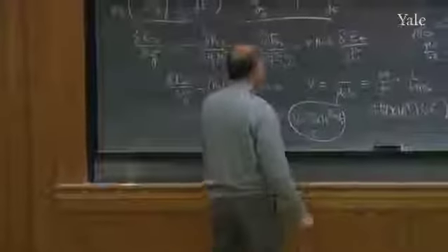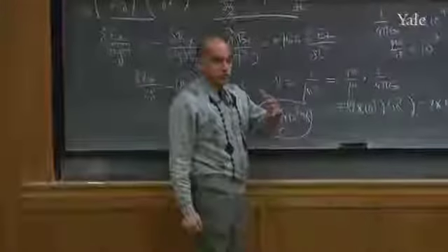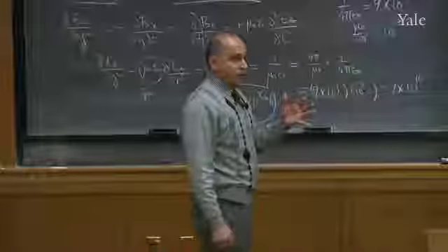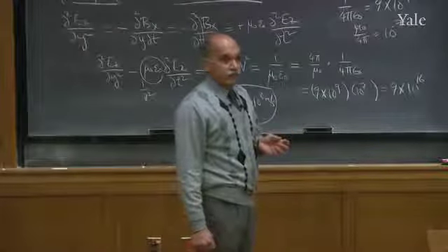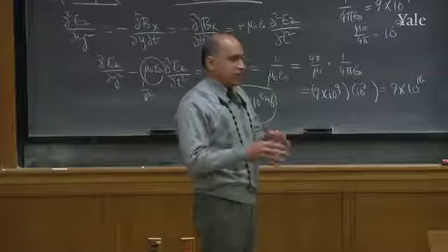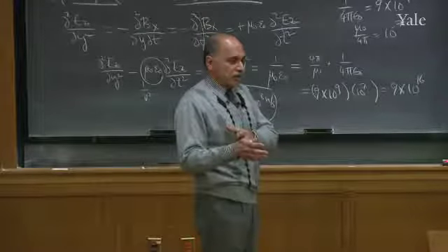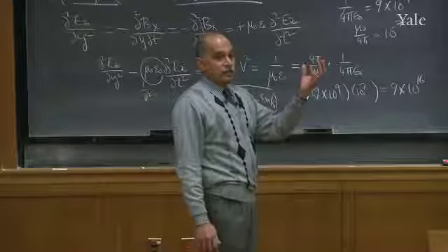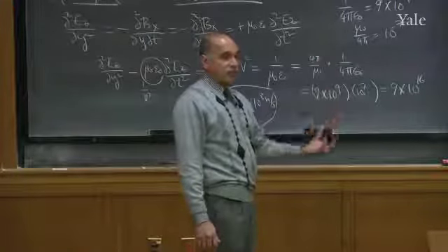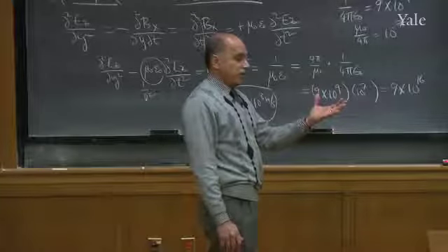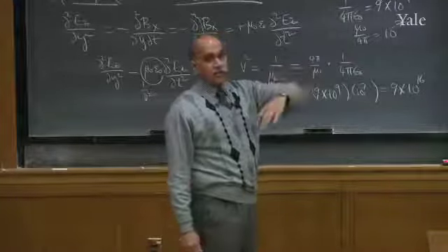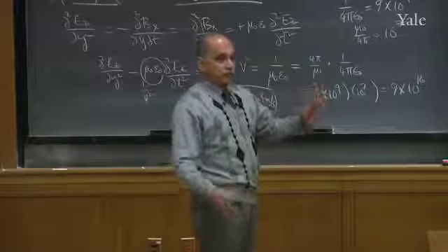So the reason electromagnetic waves travel in space without any charges is that once you've got an E field or B field somewhere, it cannot just disappear. It's like the LC circuit. If your capacitor is charged, by the time it discharges, it has driven a current in the inductor. Inductor is like a mass, and current is like velocity, so it won't stop. So the current keeps going till it charges the capacitor the opposite way. Then they go back and forth.